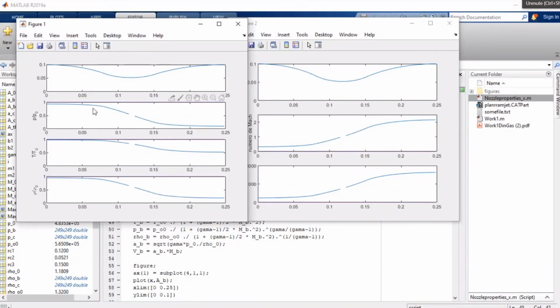Yeah, that's good. They're quite good for the reason. But don't forget that it's always better to plot the bell nozzle and the conical nozzle. And the same thing on the pressure ratio, but in a logarithmic coordinate, because I think the graphics make a sense, smoother shape. There is variation between very big values and very small values at the exit of the nozzle. And also do not present in this aspect ratio because they look very long.